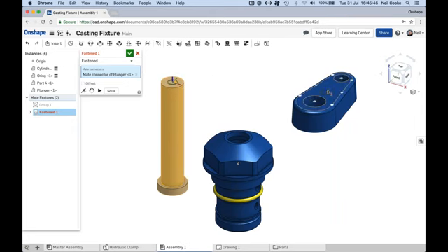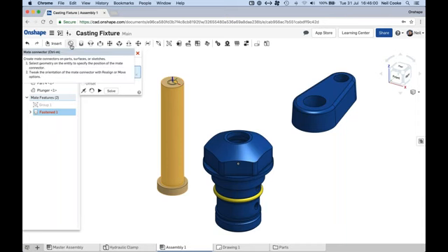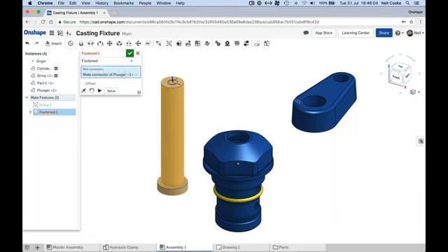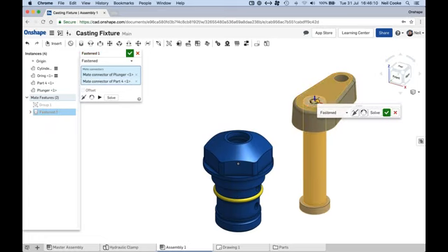Now, these will appear at the center, the centroid of a face, the center of a circle, a vertex, the middle of an edge, and these will appear here. So you don't have to create these up front. There is a special mate connector button there if for some reason you need to construct a mate connector in a certain position, but they are created on the fly. So simply go to the mate command and pick fastened, and then click the 2.